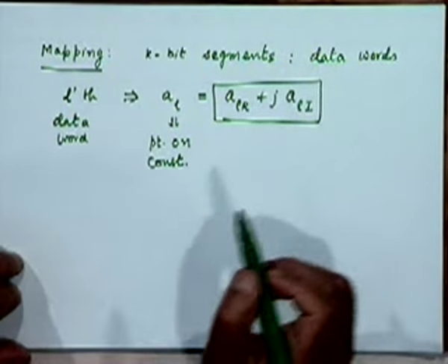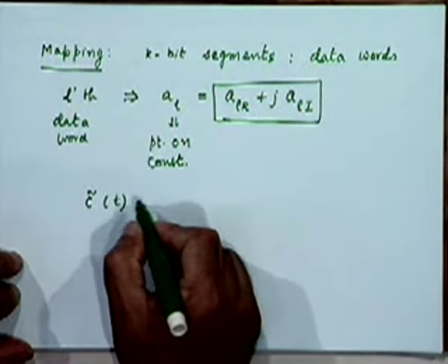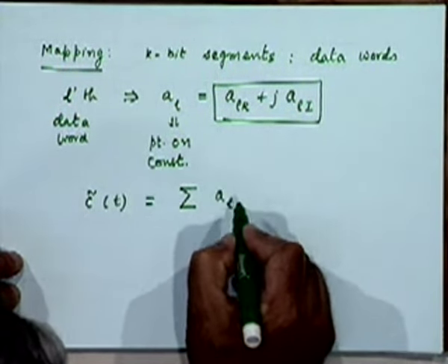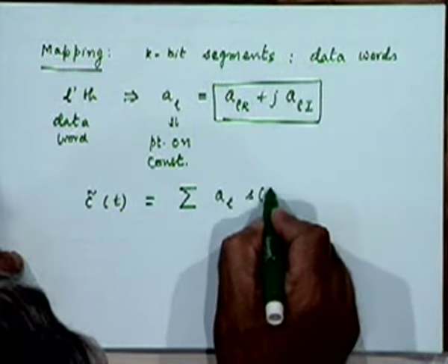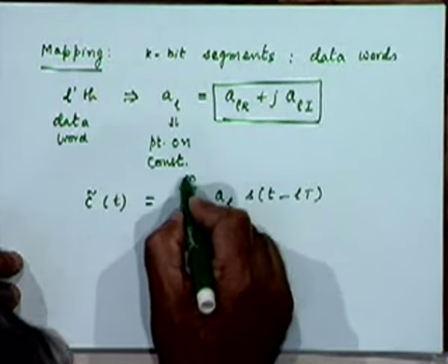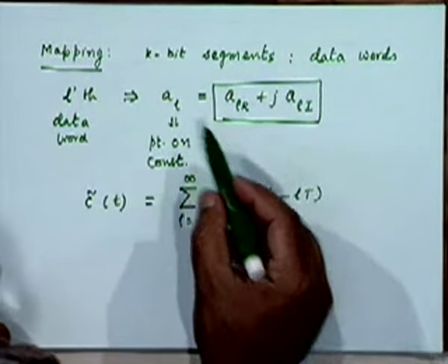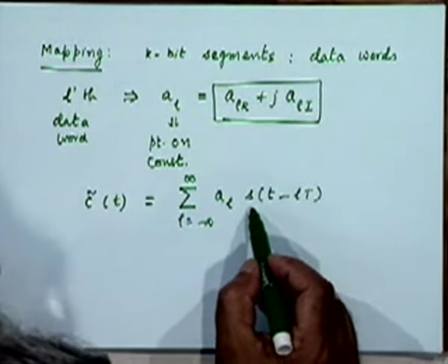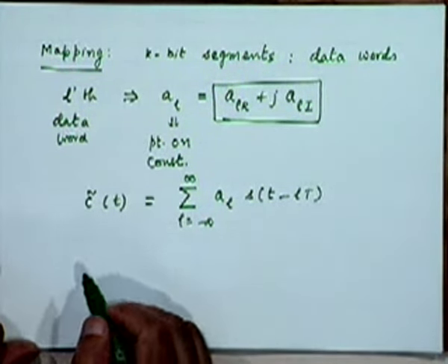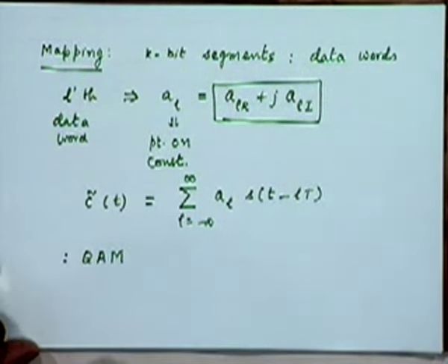So in general the overall complex signal that you are dealing with, the transmitted signal, is going to be a sequence of these with the pulse shape s(t), l going from, let's say, minus to plus infinity, right? This is your transmitted waveform where these a sub l essentially govern the complex amplitudes of the transmitted pulse. That is what we call QAM mathematically, right?